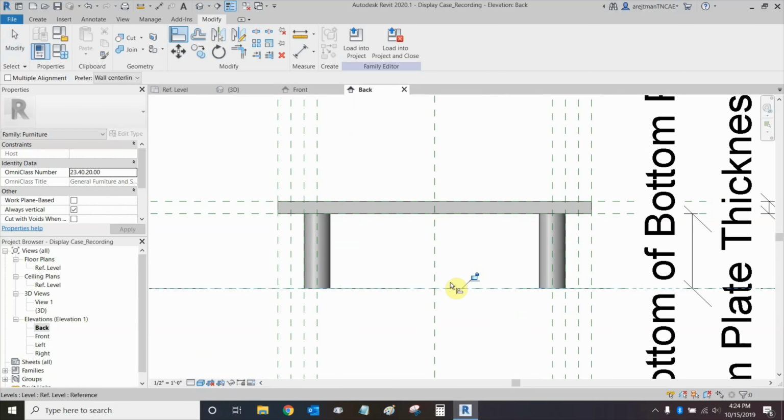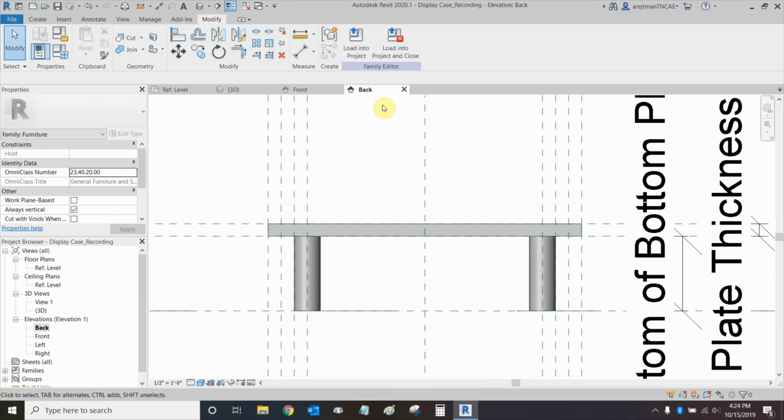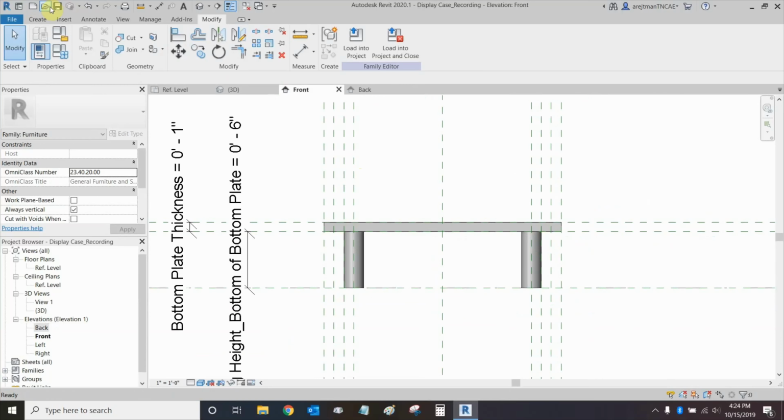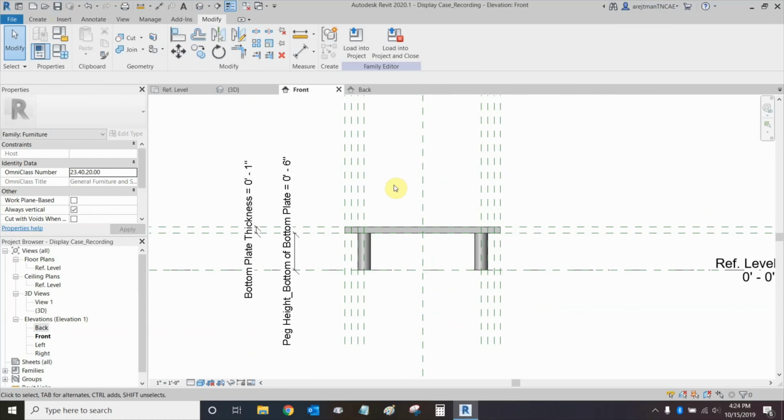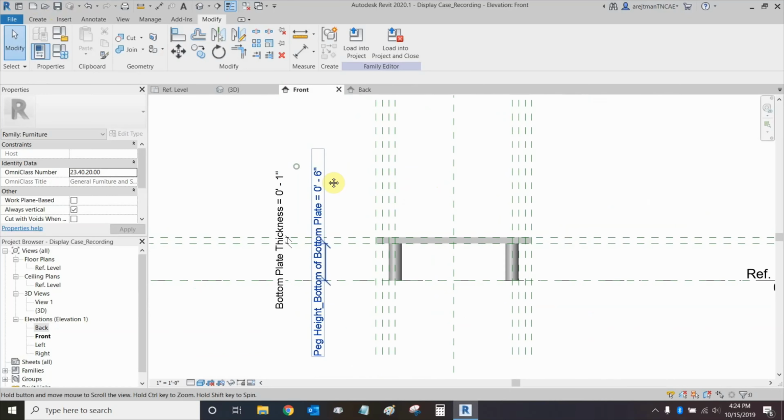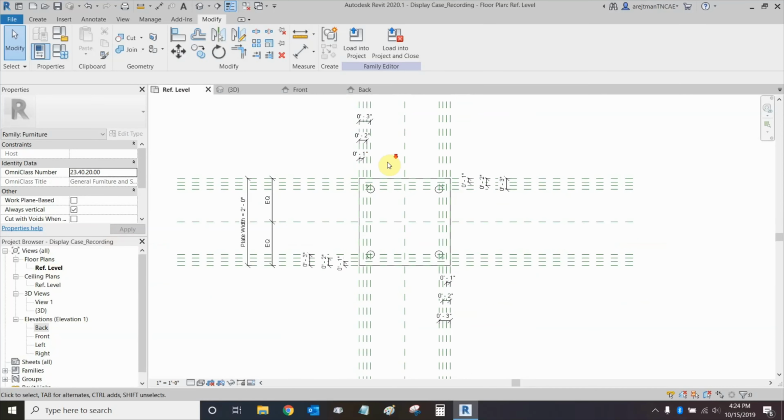And let's do the same thing to these back pegs. We're locking it to the reference planes, not to other objects. It's very important that you use the reference planes as our guides and you don't link them to other objects. That way, if you want to change a constraint, it doesn't have to change the other object. Each constraint is kind of independent from the others. All right, looks like we have everything ready. We're going from the bottom up. Everything from the bottom up looks good.